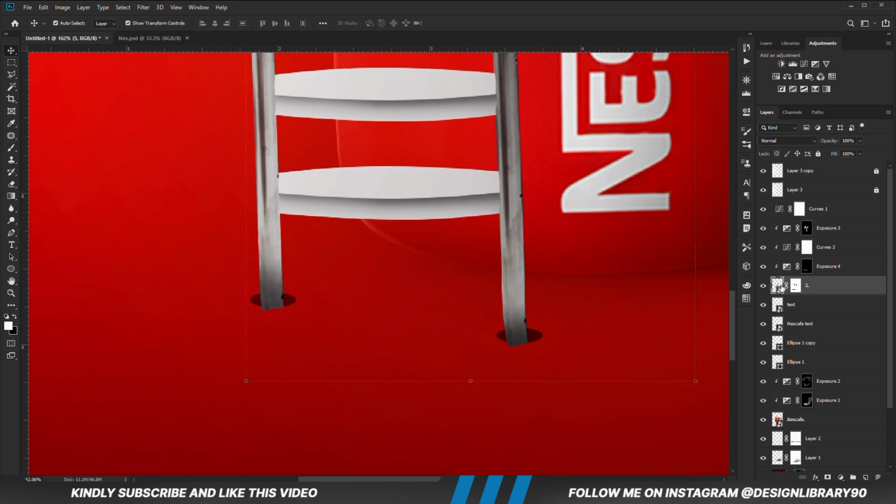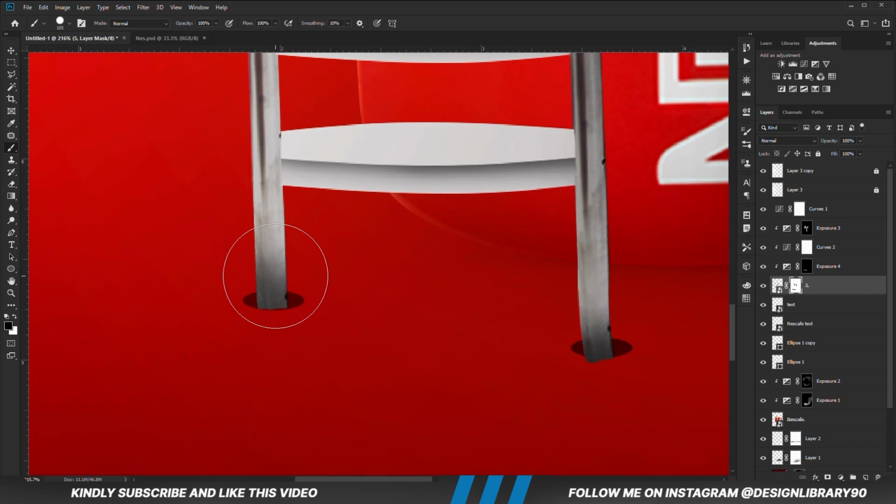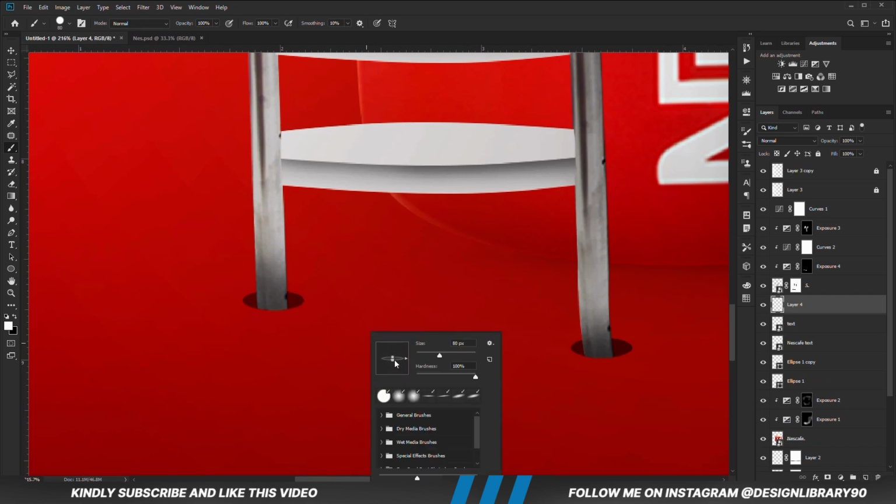With the layer selected, we are going to select the mask. Hardness is set to 100, opacity is set to 100. Foreground is set to black and we are just going to mask out this portion. We are going to create a new layer right here. We are just going to be painting more shadows right here.